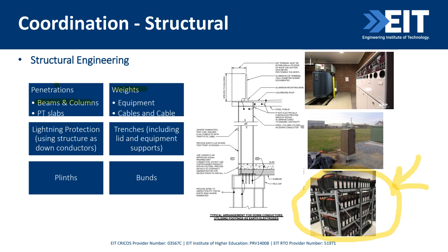You might also have very heavy equipment, like a transformer. So they need to know if there's any large equipment with weights going on their floors, or even being suspended if you're planning on hanging something from a roof, like a light fitting or a cable reeler. They need to know to make sure the roof is designed properly.